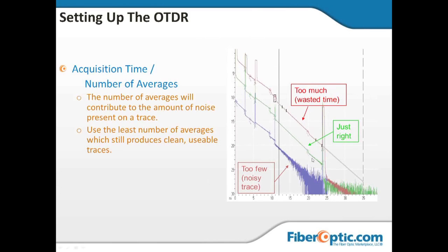Yeah, I'd probably just change the pulse width setting and do it with a 30-second test and get on with life. So again, here's another place where you're balancing. If you're shooting 3 or 4 fibers and you want to wait for it, well, a couple of minutes is no big deal. And maybe that gives you a chance to use one smaller setting on the pulse width. But if you're doing a lot of fibers, you're going to find that sweet spot, and you're going to go for like 30-second tests and get on with it.